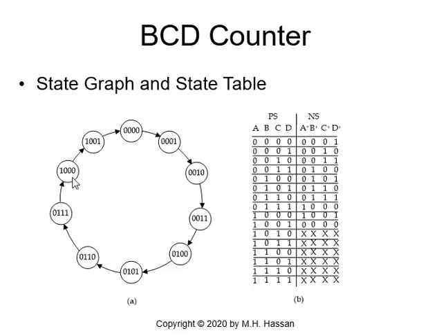So the state graph of the counter: if we are in state 0000, we go to 0001, we can name this S1, then to 0010, 0011, and all the way to 1001, then back to 0000. Now, how about if I have a state after the 1001, like 1010? The next state is all don't cares. I don't care where to go.